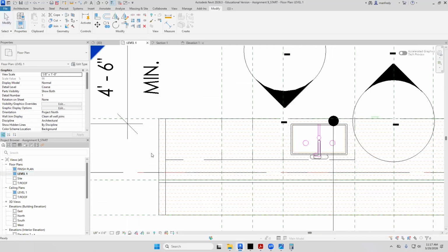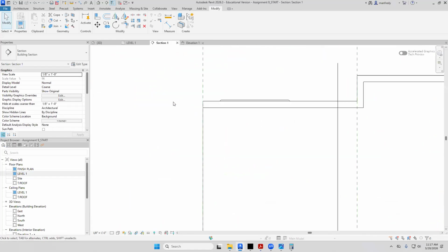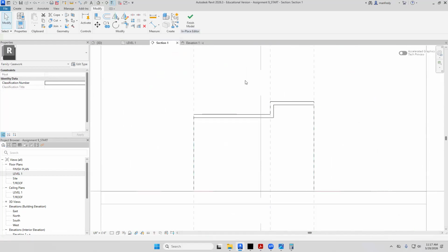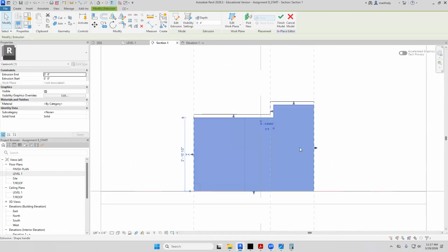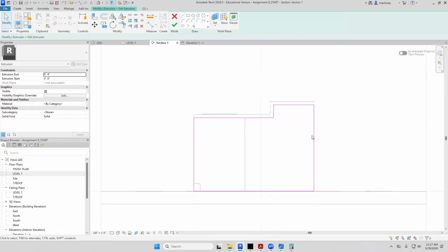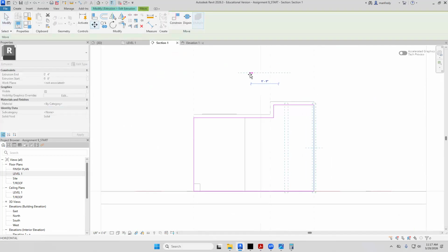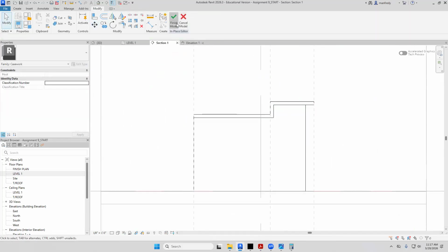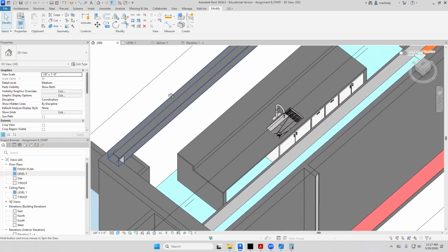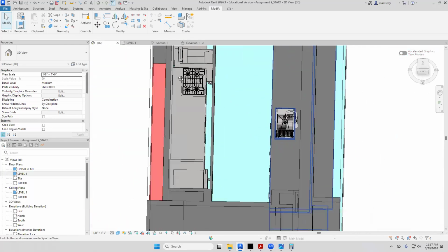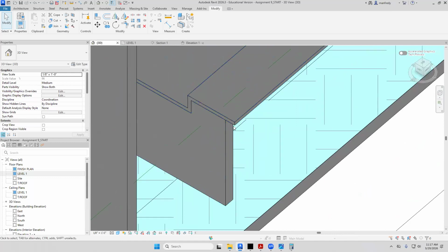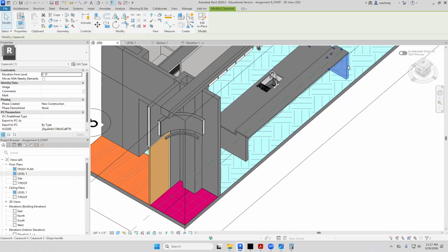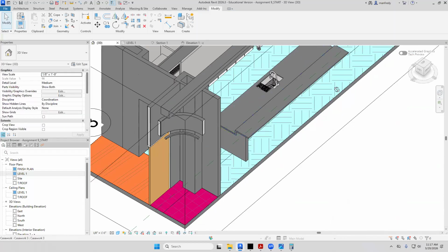So to make those changes, you can do that from the side view here again. This is the side view of the wall here. I can go edit type, grab this countertop and just move this back, or go edit extrusion and move this line back 4 inches and accept it. And that'll basically get set back like this. And then copy it to the other side so they're both the same. So I can delete this one and fix it. Copy this over to there.